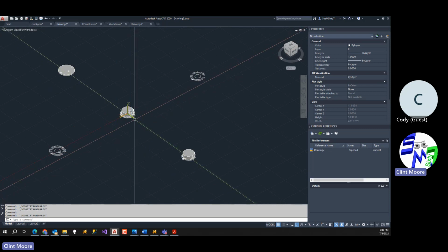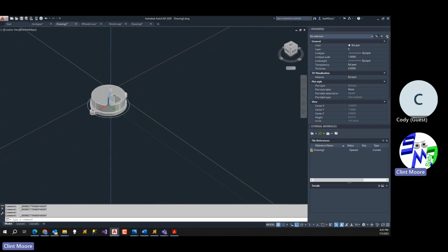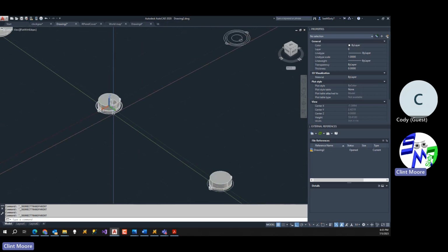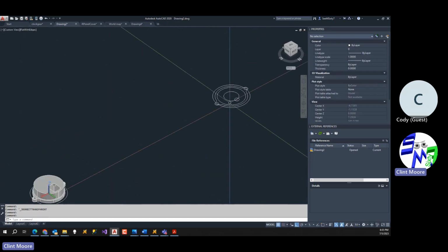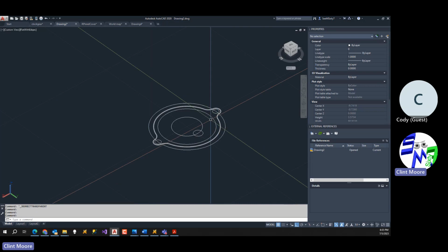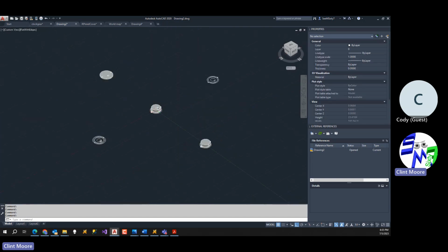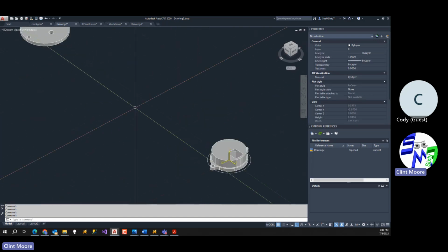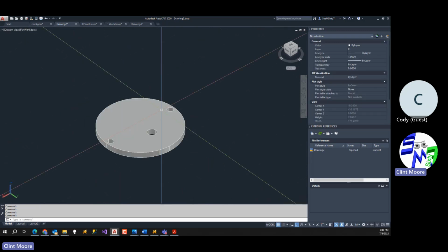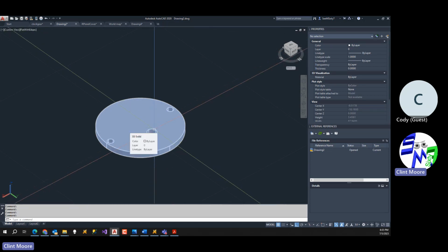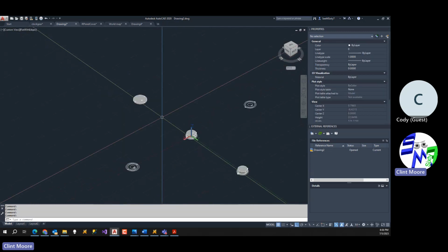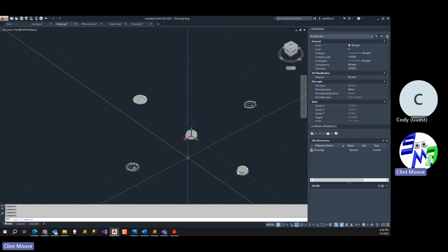What I typically do when I'm doing my model is I will start with my model in the center, and when I get to particular points, or I'm constructing it, I'll make copies of items in different locations. Like here, I was testing this up here. I made a copy of the base, and then I just printed it out real quick to make sure I had the alignment correctly, because I didn't have anything really well to test the angle of the circle that was actually on the base. It was actually 5 degrees off center. So I went ahead and rotated it out 5 degrees, printed that out, tested it, and worked like a champ.